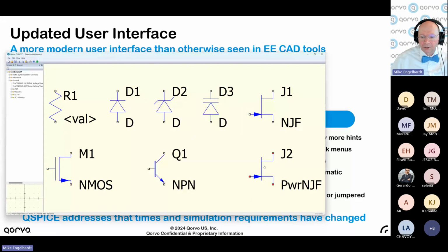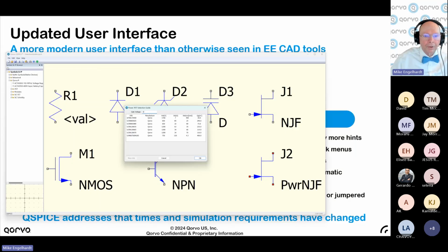And that comes into JFETs too, because JFETs are usually run with, when you fully turn on a JFET, you usually have zero gate-source voltage, and you can sort them by RDS on. But if you have a wide bandgap JFET... well, actually, any JFET, if you forward bias the junction on a JFET, it costs you some current, but its gain keeps increasing. If you've got the current, it's got the gM, and now they usually run at 0.